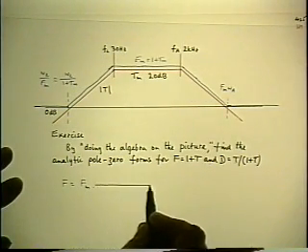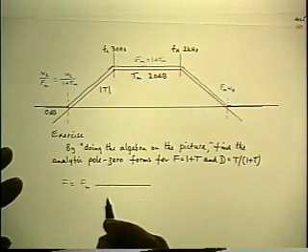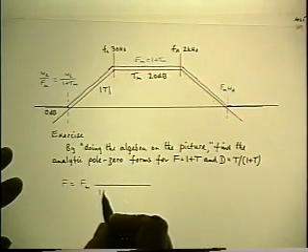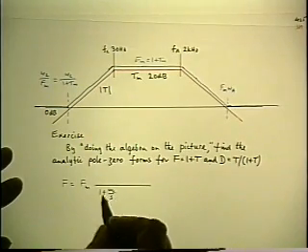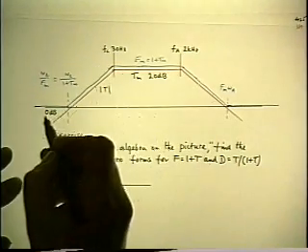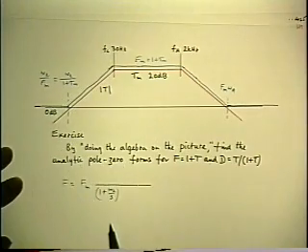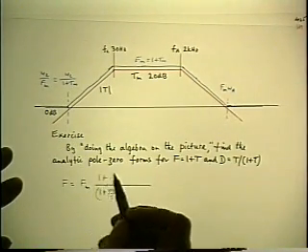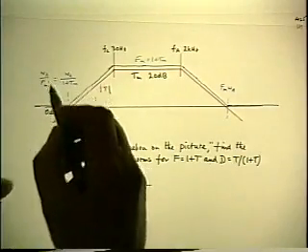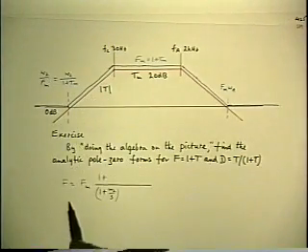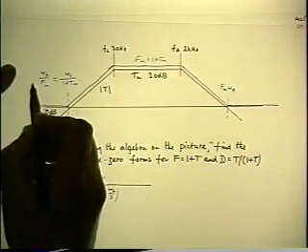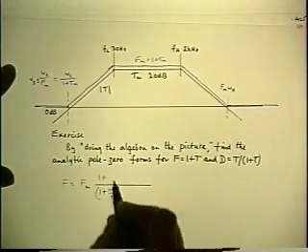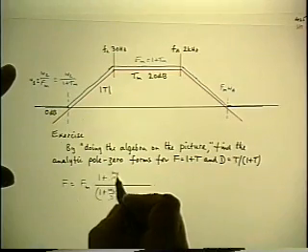And as you look down in frequency, at first you're going to encounter a concave downwards corner. So that's an inverted pole at omega 2. As you continue to look down, you have a concave upwards corner. So that's an inverted 0. Now I could write this value out here, but instead I'll define a new frequency. I'll call this omega 3. So I'll write that as omega 3 over s.